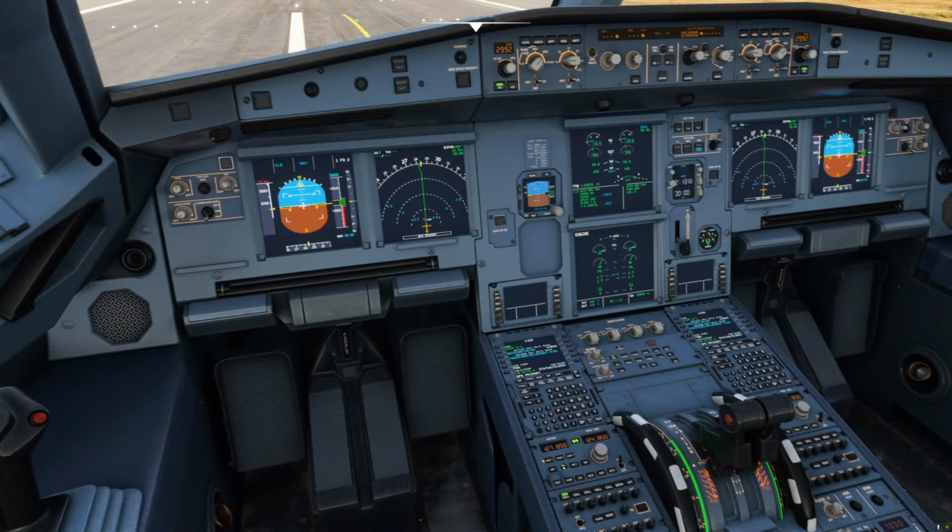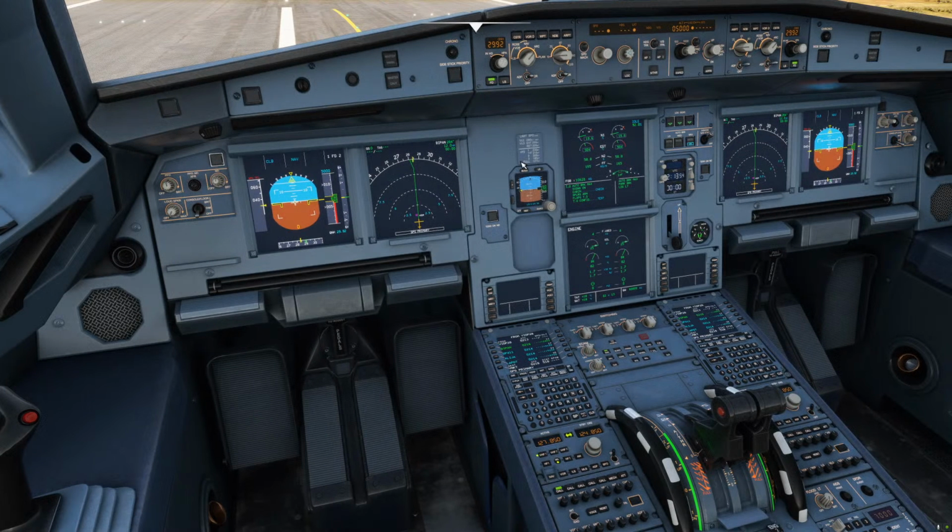If I show you flight plan, then I will click on flight plan, and if I scroll through, let me select it to plan, and the range is 10, right? So if I scroll through our flight plan, it will show you our whole route here, and you always have to check it after loading flight plan. There should not be any discontinuity. So you can see we are good. The last waypoint is VNKT. So let me set it back to arc. Range is 20, both sides, and let me select constraint, both sides, and it looks good.